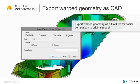So the way we can use this is to export the actual CAD model as a warped CAD model, and you could possibly use it to prototype that particular warped part and see how it fits into an assembly in reality. Another way you could use this is to export the windage, the opposing warpage, so you can build your CAD system, your tool, around that as a windage model.